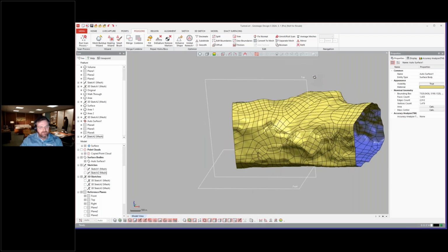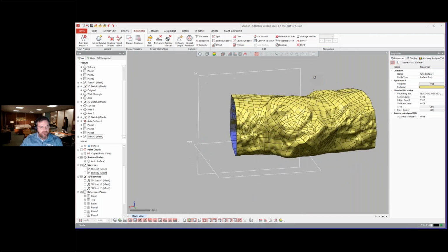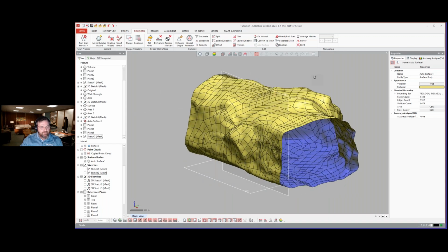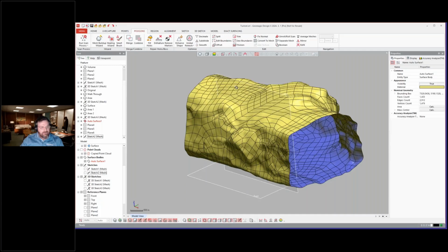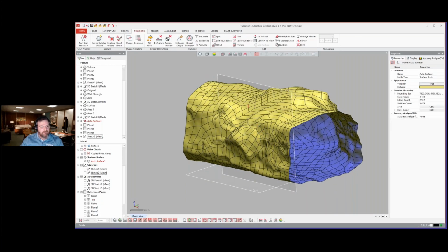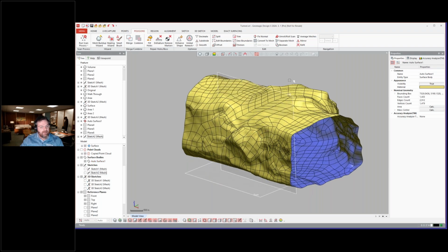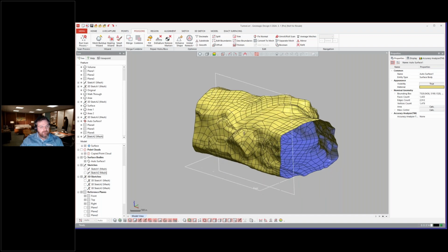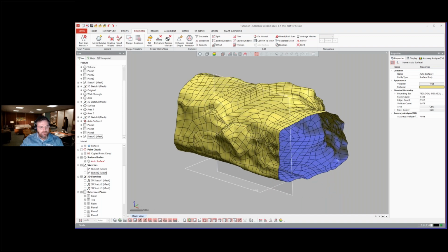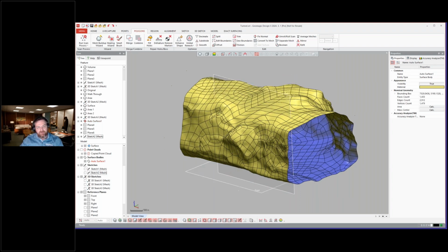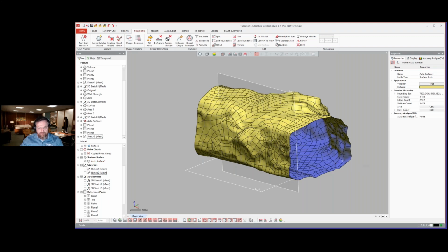You could have done this for the entire thing, but I was just taking a certain section of that and creating a NURB surface from it, and saving that out as a STEP. I just said neutral, all those different types of CAD formats. So if you needed to extract some of this information and get it over to another software package, I know that some of this long range stuff is done in, for example, an Autodesk application or something like that. You can write out these CAD objects and send them over there and bring them in.